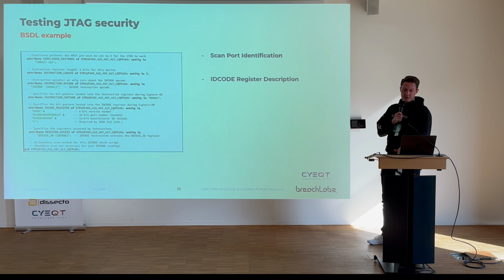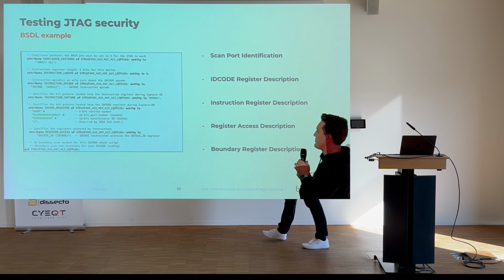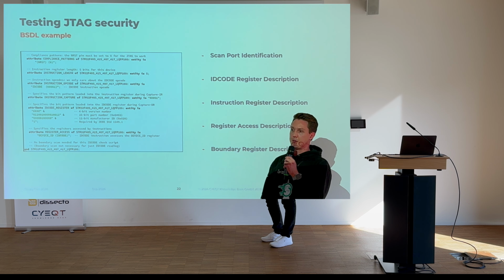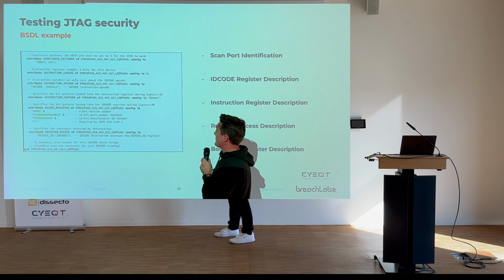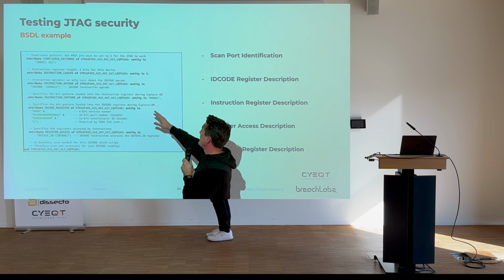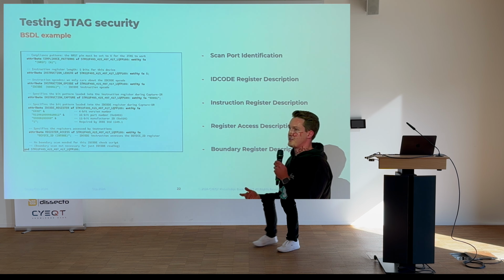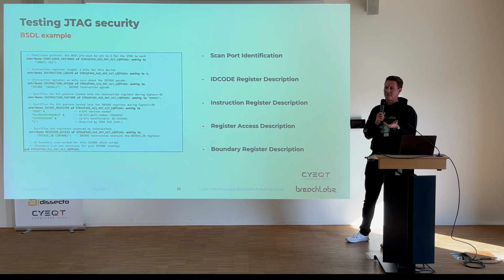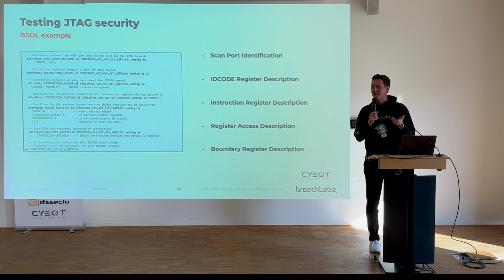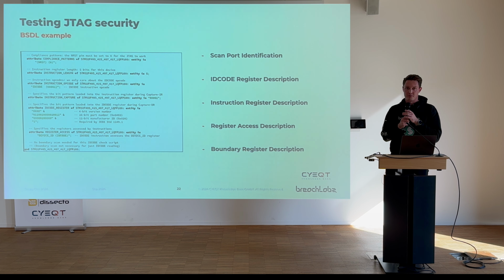I will quickly run over those. Those are not that important. But this actually gives you one piece of information that is very crucial. You can determine this experimentally, and I'll quickly ask you in a second how you would do that. But for example, this is one thing you would have to keep in mind: the instruction register length. You have to have the correct instruction register length when you talk to a chip in order to actually get some feedback. Okay, there we go. Quick overview.